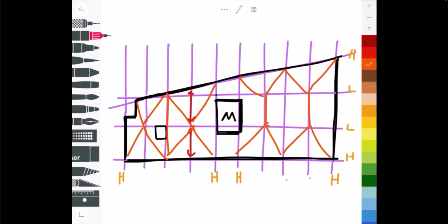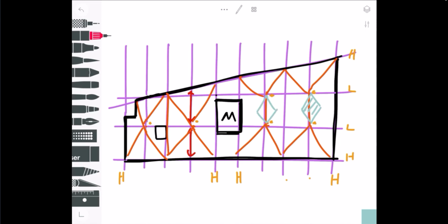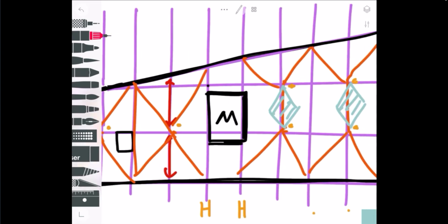And now what I would do in this case, let's just put in some roof drains here in a different color. So we'd have a roof drain there, and a roof drain there, there, and there. We'd have one around here, and we'd have one there. And then we'd have our sloped insulation at these flat spots. Okay, like so. And those two are okay. Now we've pretty much put two high points here on each side of the mechanical room, and I did that on purpose. It just happened to work out that way.